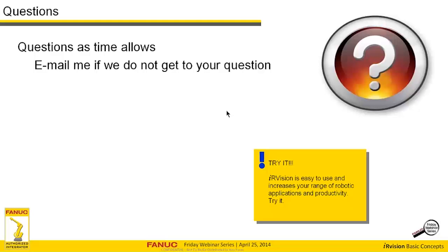But whenever you're calibrating a vision system, you want your calibration data to encompass the entire field of view. So you can imagine when you have a large field of view, getting a grid that's big enough. We don't provide grids that are big enough, but using robot generated grid cal, you could calibrate the whole field of view, because the robot is going to move to the entire field of view and generate data for the entire field of view.